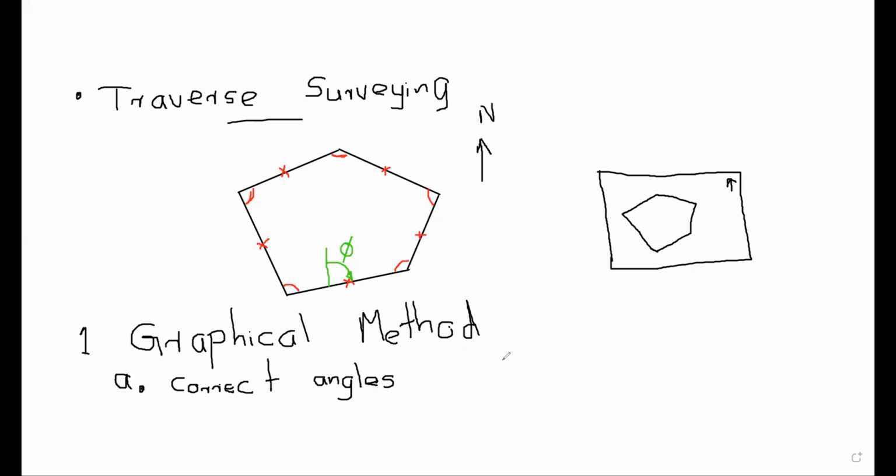So how we can correct? You take sigma theta, that is theta 1, theta 2, theta 3, likewise, you have the internal angles, etc. Never mind how many nodes you have, but they should be the internal angles. Then you can correct them. So first you can sum up. You can add all your internal angles.